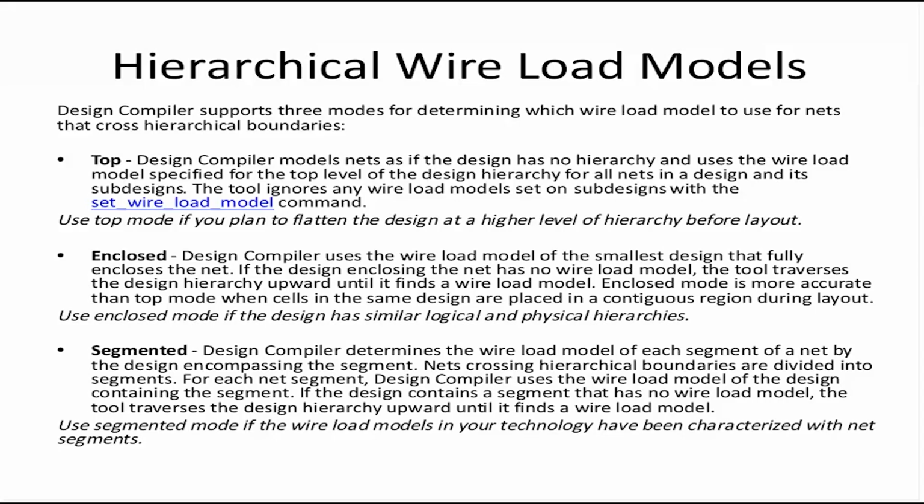In this case, for each net, DC will simply use the wire load model that is used by the top level of the design. The tool ignores any wire load models set on the lower designs with the set wire load model command. You can use the top mode if you are planning to flatten the design. If you are planning that all the hierarchies will be removed after synthesis, then we can use this. Obviously, this is the most crude form of wire load mode.